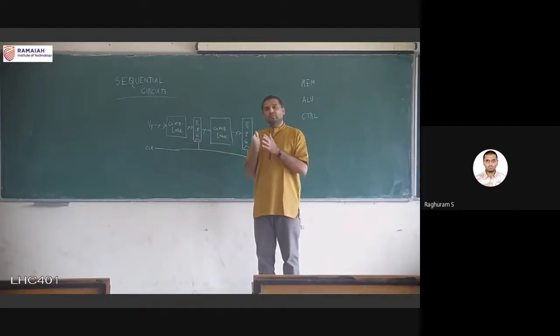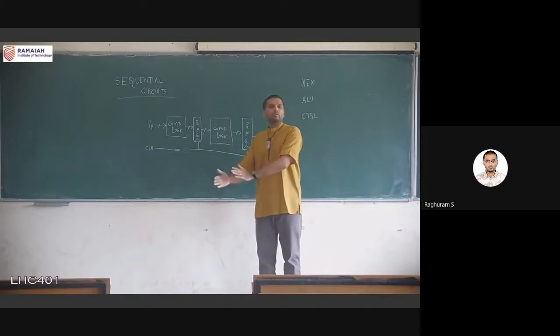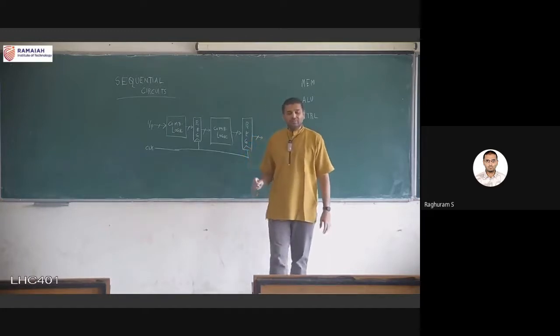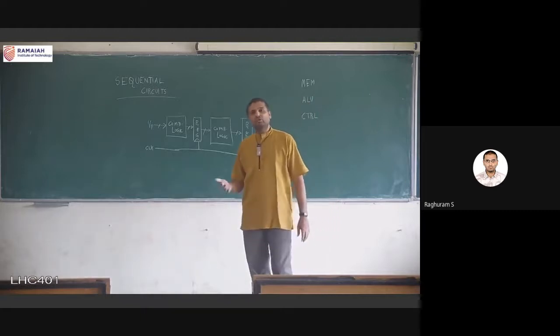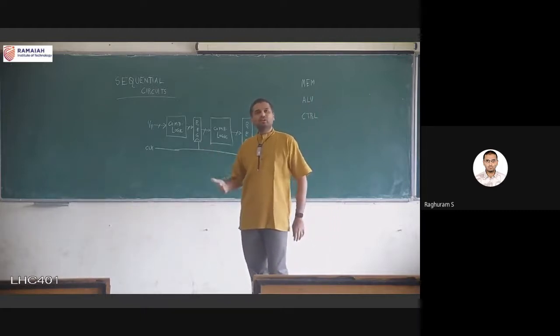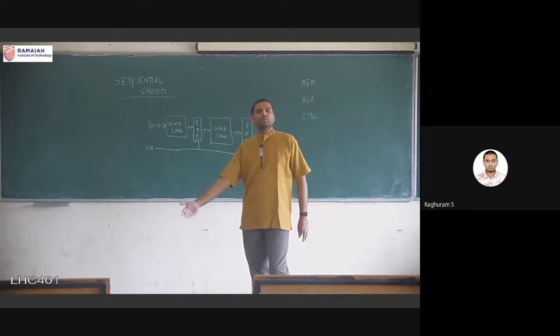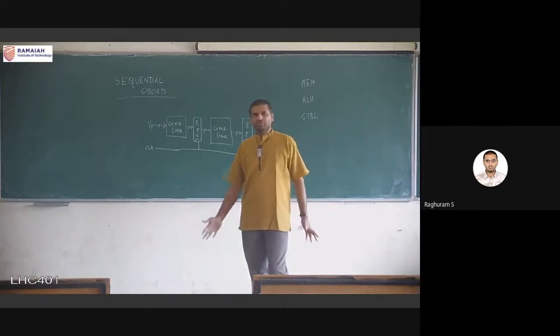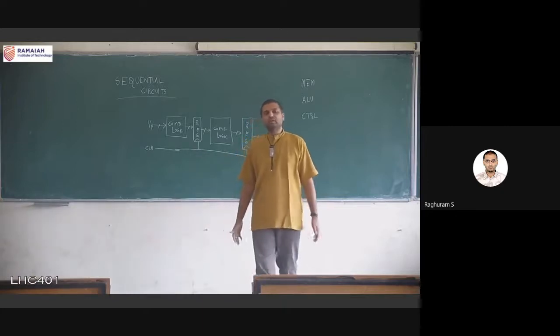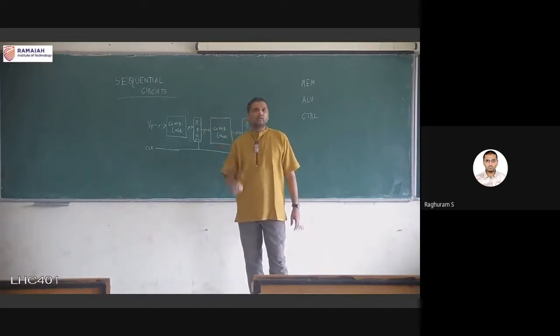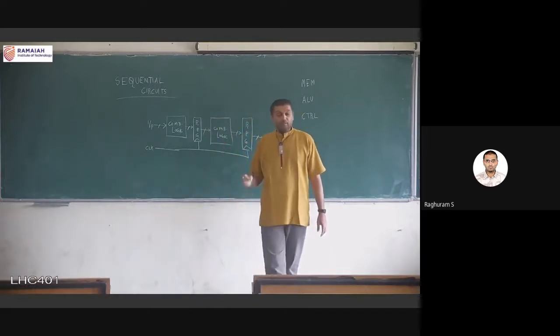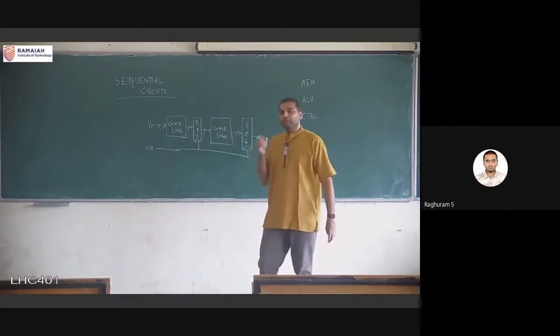We need to make sure that our signals are proper before we give them to the next block. Is there any other way? Can you think of one way to make sure that the signals are being synchronized properly before giving them to the next block? It's not possible. The only way is to synchronize everything to the clock edge. And this is also a perfect example of the locality rule.